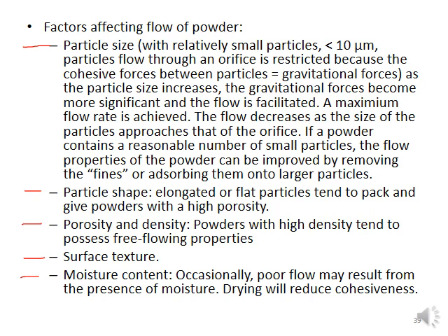Moisture content. Moisture content, up to a certain level, of course, increases the attractive forces between molecules. Therefore, drying might reduce cohesive forces between the particles, and this will improve flowability.